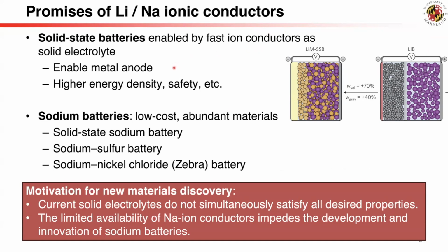They have the potential to enable high energy density metallic anodes and also improve the safety and other attributes of the battery. In addition to lithium solid-state batteries, sodium batteries also have a lot of advantages, such as the use of low-cost and abundant materials. They include the solid-state sodium battery, sodium sulfur battery, and those high-temperature molten salt batteries. There is a lot of interest in developing new materials because current solid electrolytes do not simultaneously satisfy all desired properties that are required to develop this new battery technology.